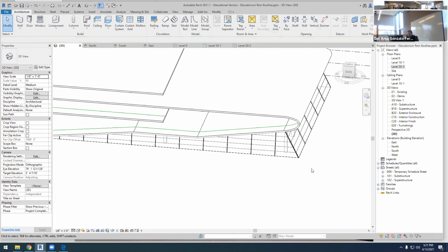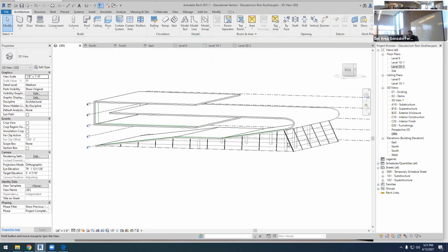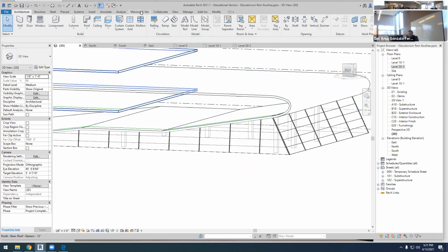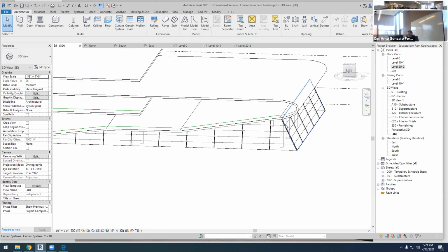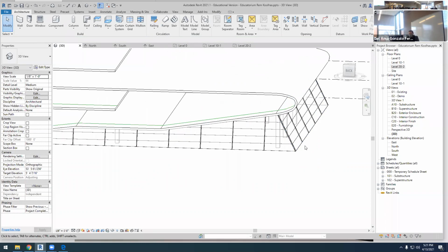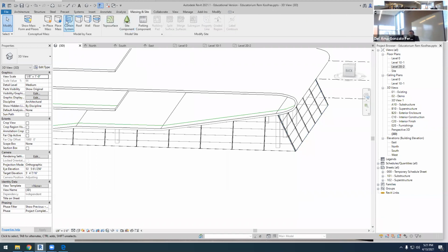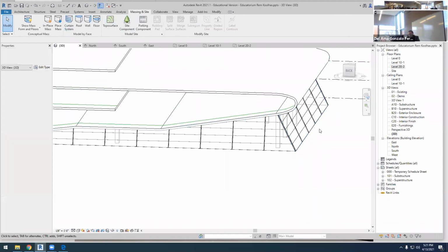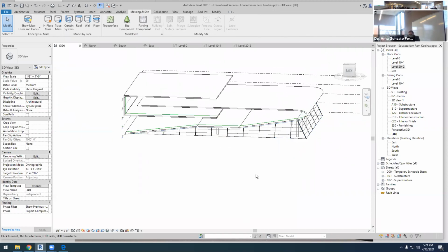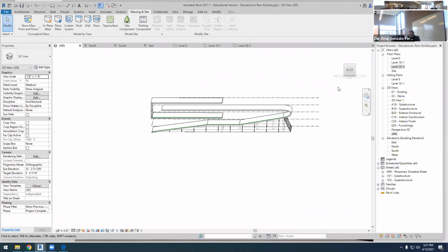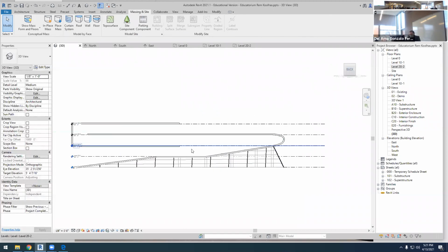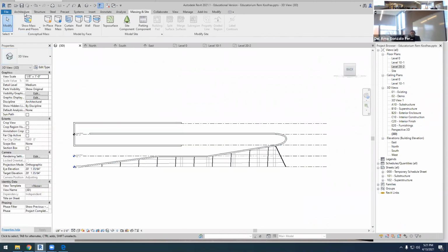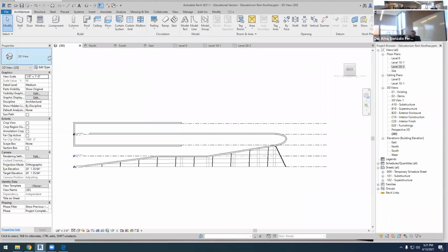Well, there's a way to do this without the massing and site component, but if we have tilted surfaces, it's the easiest way. So we can create this, select the massing and site curtain system, and then create the curtain wall. For this one, I think I would use the architecture wall, if you don't have the storefront.